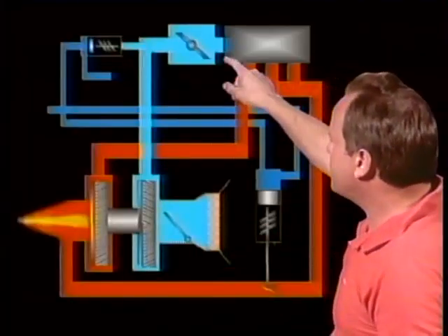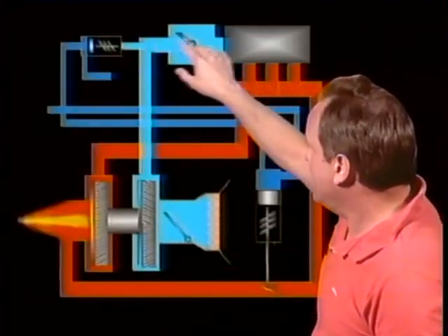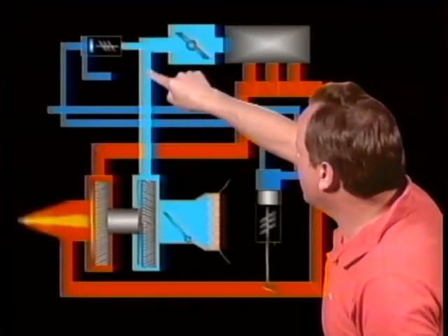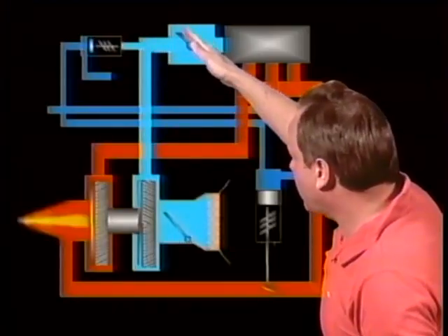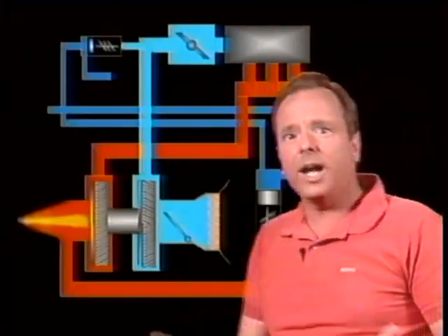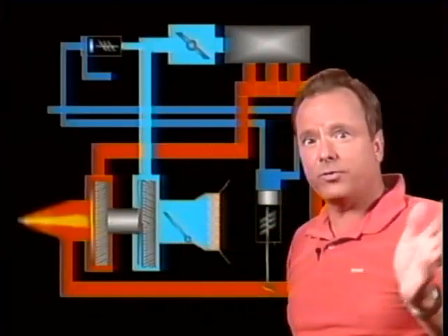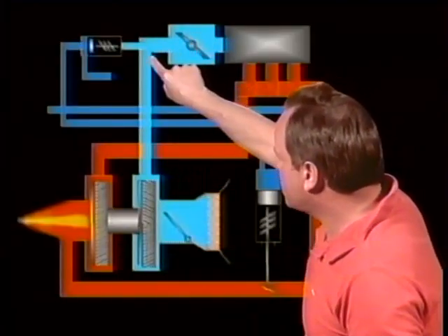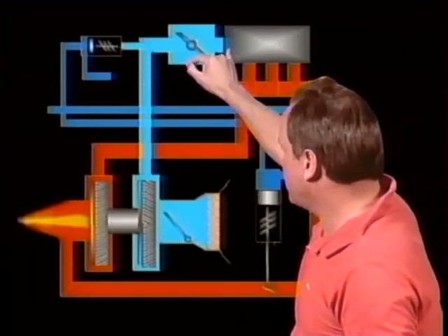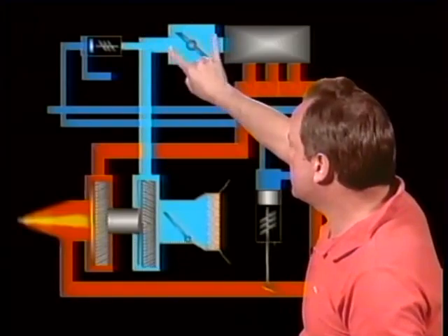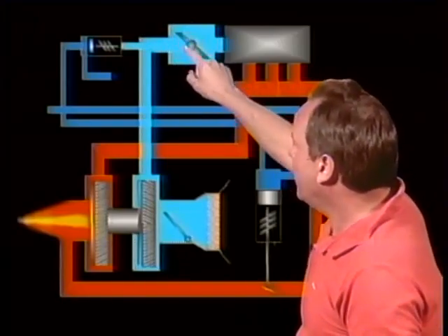The differential pressure controller senses the pressure just before you get to the throttle valve and the pressure after you get to the throttle valve. And it says, look, I want there always to be, and I'm going to make this figure up, 2 inches of manifold pressure difference between the air pressure before the throttle valve and the air pressure after the throttle valve. That differential pressure controller maintains 2 inches difference between the two, and here's the way it does it.